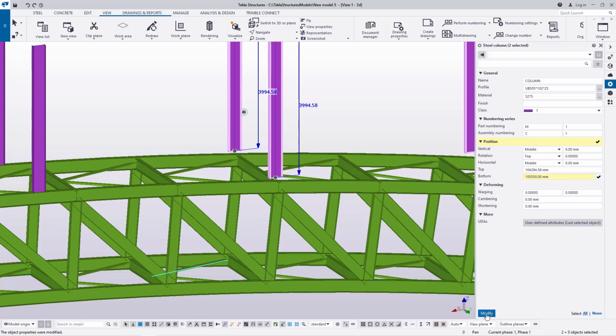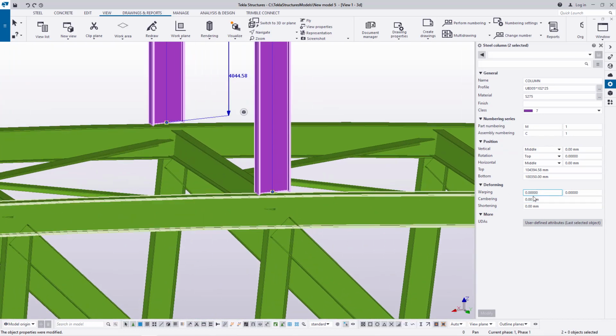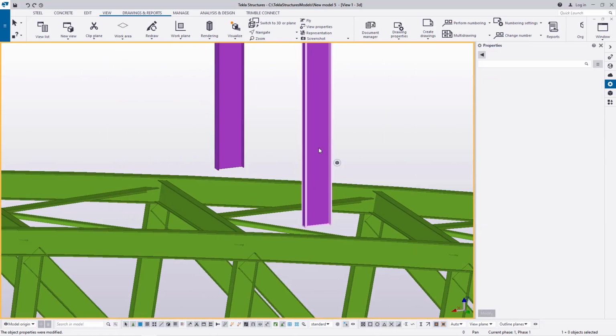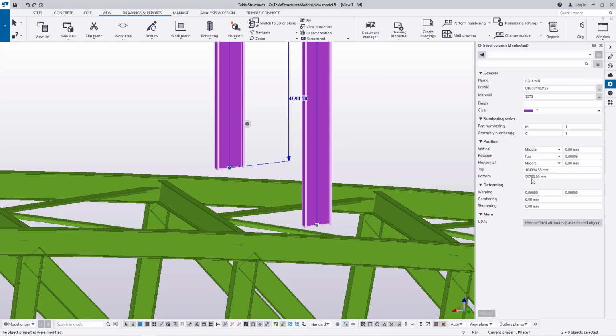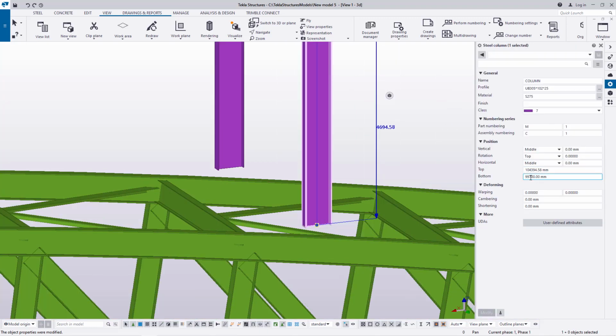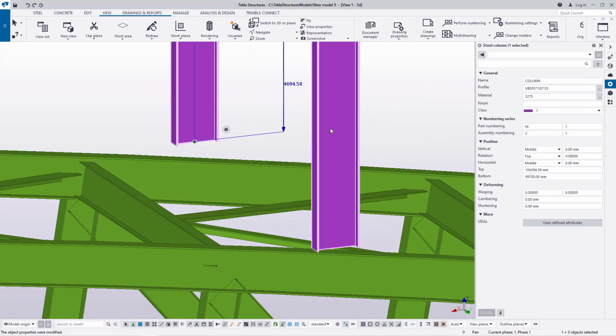This will work much better. We can change this to 30 or 3 or 2, and that one will make that still sit on top of that curve. This one also, we just double click on that, and we change this. Instead of 700 here, we feed 600. Let's undo that. Just double click on it, and instead of 7 here, we feed 6, and that will land it on top right there.